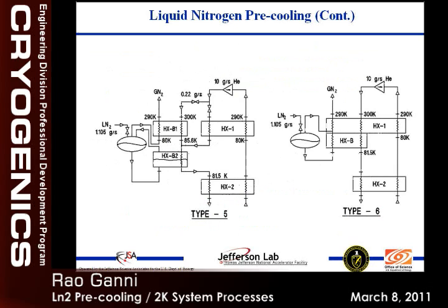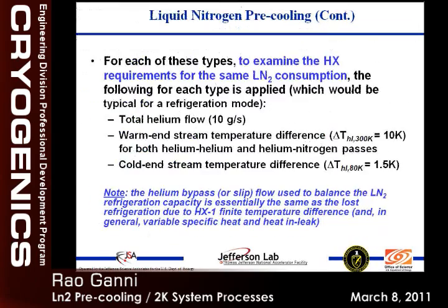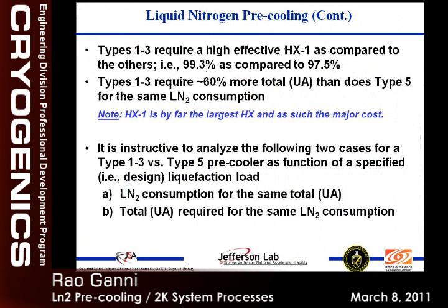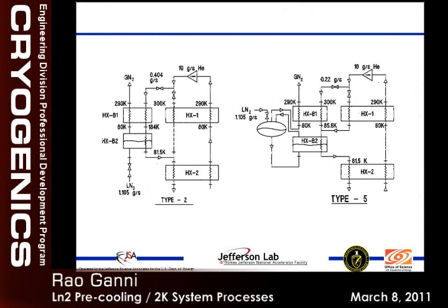This is full of liquid nitrogen, and when it is driven by heat, by gravity, the flow circulation through this is normally anywhere from 10 to 20 times more than it can all vaporize by mass. So this interface moves when they control the amount of nitrogen they are putting in by this temperature. It always moves here in this interface region. So it's very hard to control the liquid vapor interface here, which is a problem for controlling this temperature. The whole refrigerator will lose heat, and it has an effect on the rest of your process and your temperature stability. That's what happened for the NASA 3.5 kilowatt machines. That was one of the things that contributed to not being able to have stable temperature control at the loads.